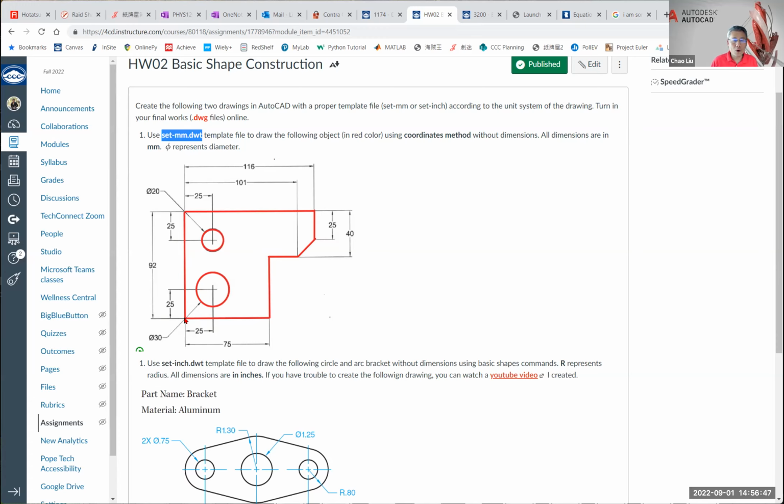Then what you want to do is to use the practice that you did for the previous lab, the coordinate system. You go to the right 75 units, which is 75 millimeters, and the angle will be 0 degrees. And you have to put the at sign to use the relative coordinate system. That is the simplest way.